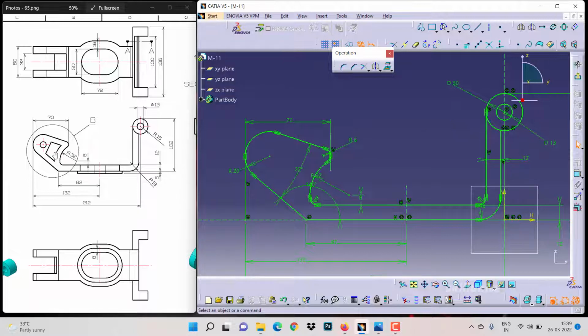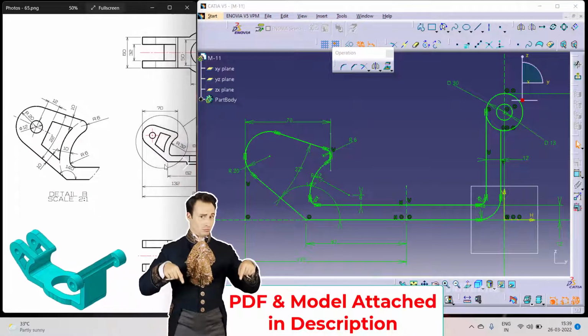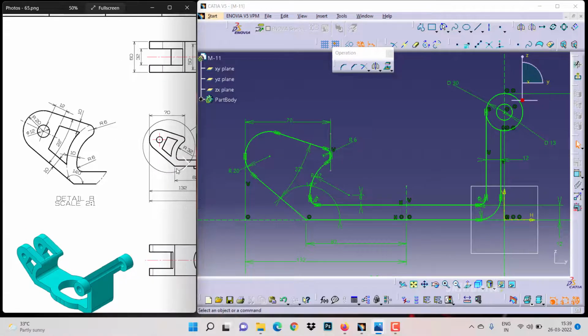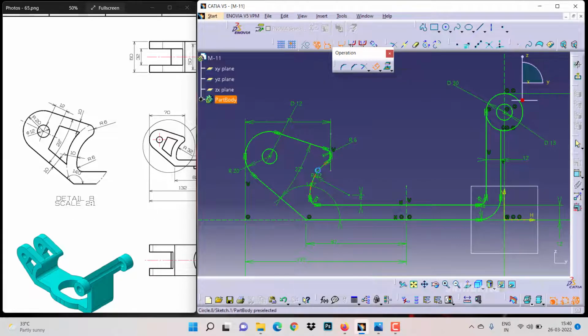So this shape also, if I want to create now itself, we can do that, or when you are making the cutouts, that time also you can do it. So better we will do it now itself, so it will be easier when we do the projection. So create your circle on the center first, so that is having a diameter of 12. So then we are having over here an arc kind, so that is having same offset type with 10 mm thickness. So we will directly go with offset option over here and select the arc. Then we will project it a little bit upward with a distance.